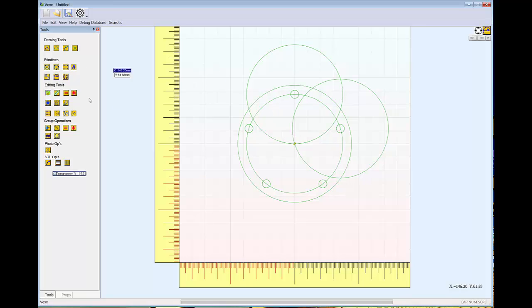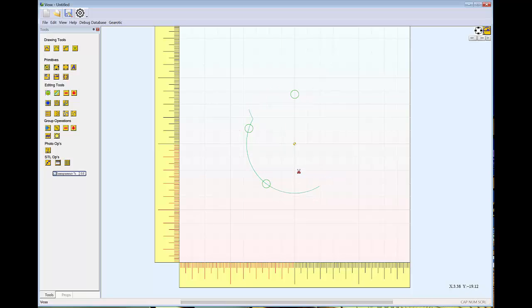I'll clip away the portions that don't belong to our vane now, such as these lines here, and we'll just clip everything away except for the points which belong to that vane. Now when you're using the trimmer, it shows red what it's about to remove, and it is possible for the trimmer to screw up just as it did right there. So be handy with a Control Z in order to undo that problem, and we can see that this will not seem to cut at this point.